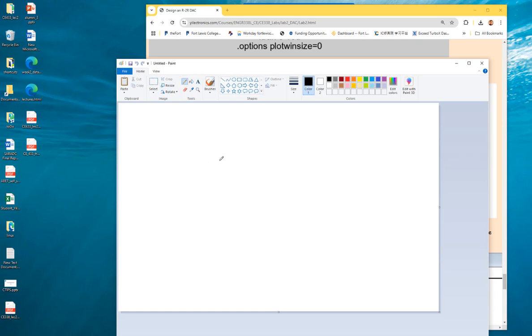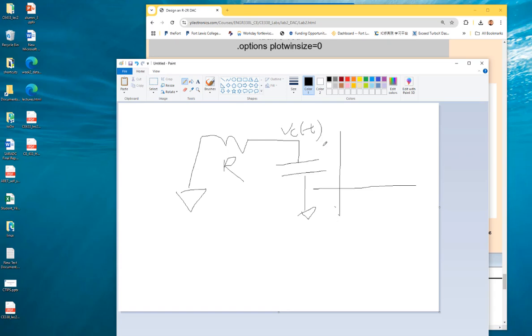which is just a capacitor discharging through a resistor, that natural response curve of the VC(t) discharging over time, so the voltage looks like this, remember? Just to kind of recall this. And this one equals VC0, the original voltage stored in the capacitor, times e to the minus t over RC. So that's times this attenuation factor over here.